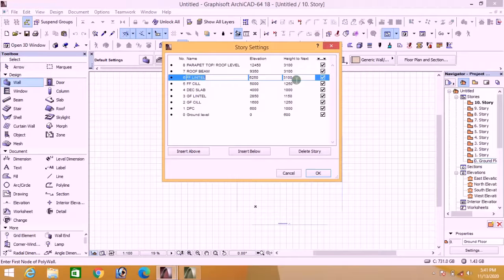Now, on top of these 2 courses of block that we have laid, we are going to chain the entire structure with a roof beam. That roof beam measures 250, which means 250 plus the 750 that we now have gives us 1000. So we are adding 1000 at this place, right? 1000. That brings us to roof beam top.